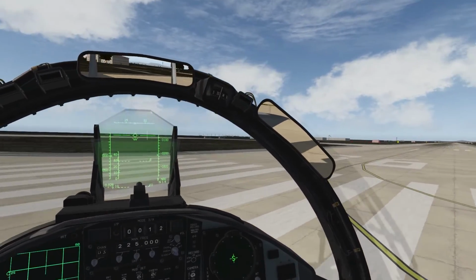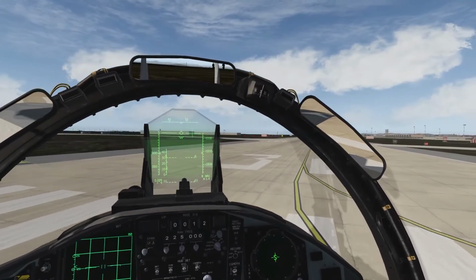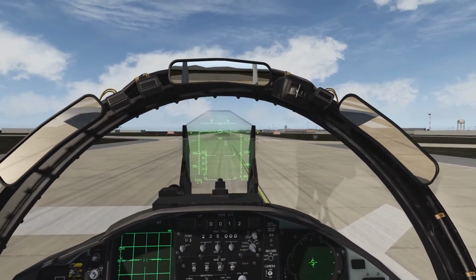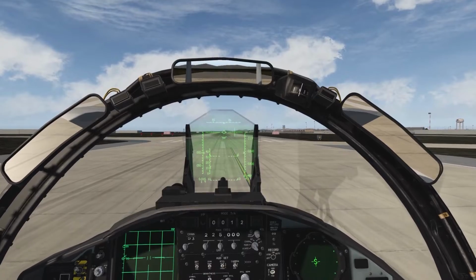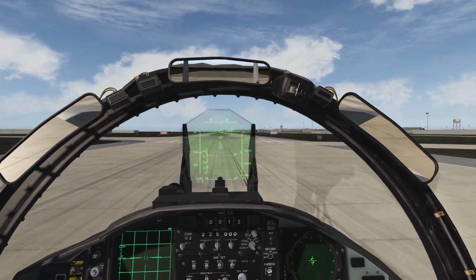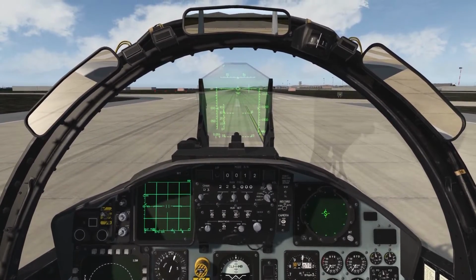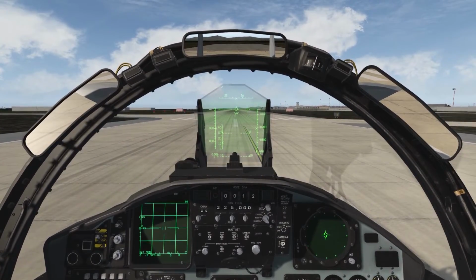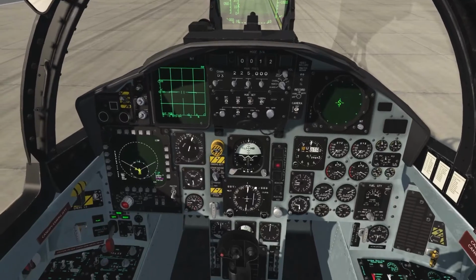The other thing to consider in the Eagle versus the Viper is the nose wheel steering. So as we talked before, it's on by default, and pressing the nose wheel steering button only makes it more crazy. So you're actually going to use the paddle switch to disable nose wheel steering. So once you get airspeed alive, I recommend depressing and holding the paddle switch, otherwise you'll be off the side of the runway in no time.